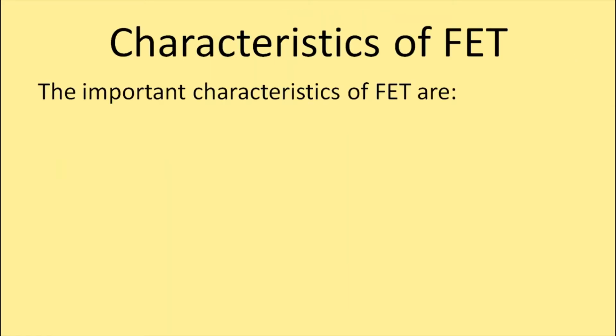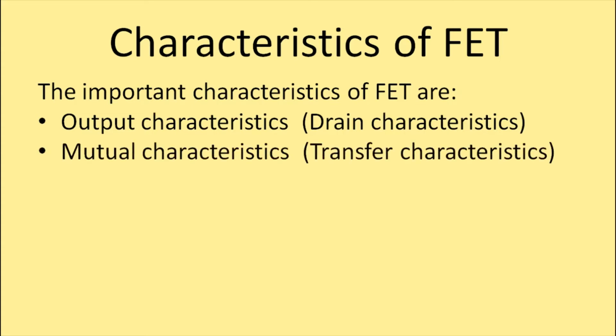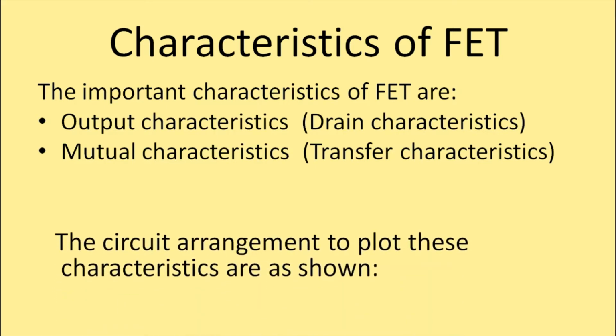FET has two important characteristics. One is commonly known as the output characteristic, also known as the drain characteristic, and the other is the mutual characteristic, also known as the transfer characteristic. Now, to plot these characteristics, how the circuit setup should be, that we will see now.